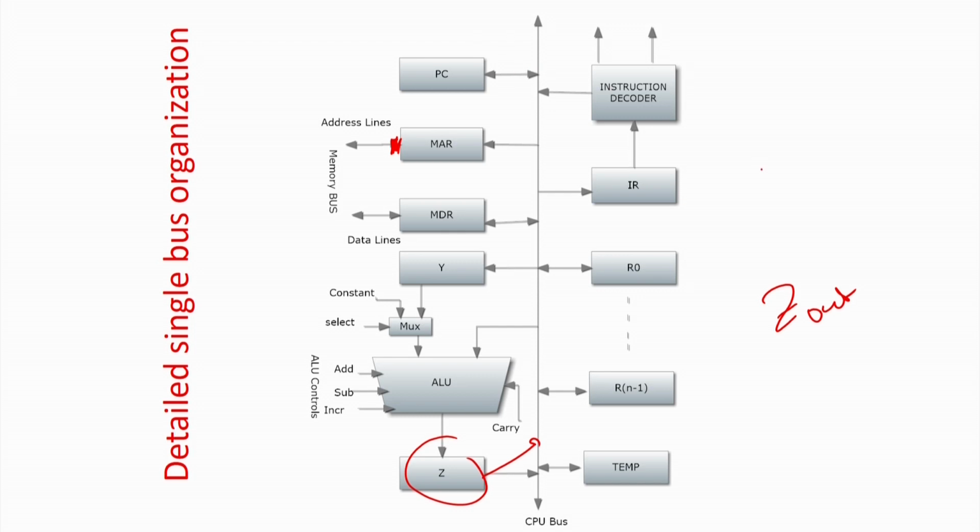In that case what will you do? You will write PC in. That means PC is going to take the input from the bus. As already discussed in the last unit, you cannot have simultaneously Z out and PC out. In this case, PC will be dumping over here, Z will be dumping over here, there is a conflict. So, those things have to be avoided, correct. Sorry, it is a bus.